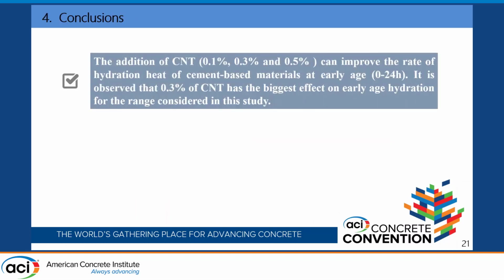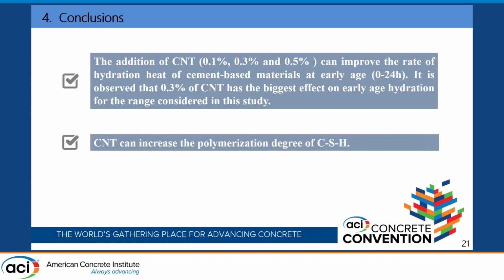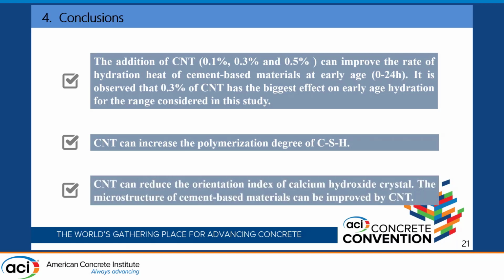So if I conclude, the main point, as I mentioned, is that the addition of CNT can improve the rate of hydration, and also, as I mentioned, the increase in polymerization and decrease in size of the calcium hydroxide crystal. So those are the main conclusions from the study on XRD, SEM, and isothermal calorimeter.